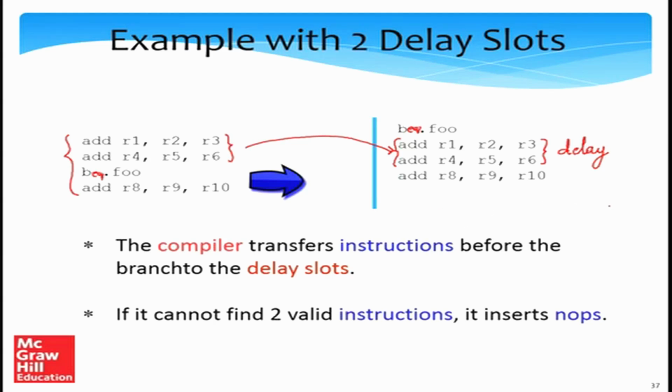So in this case, what happens is that when the branch is there in the EX stage, let it be any branch instruction, we have already fetched the subsequent two instructions into the OF and IF stages. Now if the branch is taken, these instructions would have been deemed to have fetched incorrectly. So they would be on the wrong path essentially.